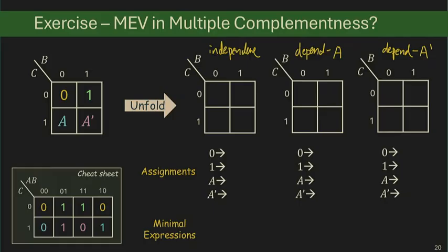F equals A, the output depends on that variable. And the output is going to be the same as that variable, given that B equals 0, C equals 1, the position of the A variable. So you have a 3-input function, A, B, C. Let's say you fix the value of B and C to be 0, 1. At that point, the output depends on the remaining variable, A.